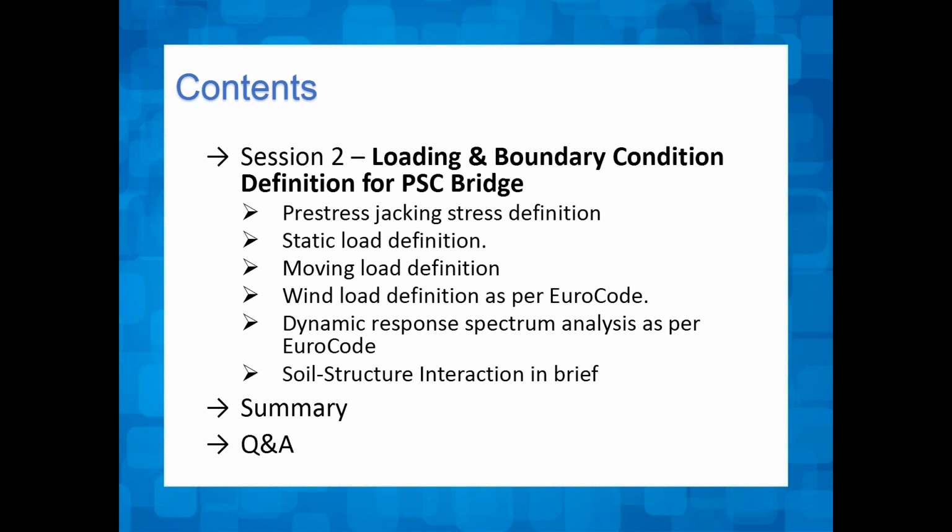As I've already mentioned, we are going to look at how to create tendons and how to apply the pre-stress tracking force. And then we will see what all static loads would be applicable. After that, we will see how to apply the moving loads on the PSC bridge that we have already modeled. Then we will apply certain wind loads. I'll show the calculations, and then we will move to the dynamic response spectrum load application. And after that, we'll have a description on soil structure interaction. We will summarize today's session, and you can also write up your questions.